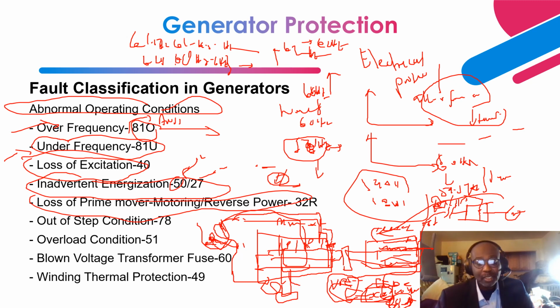So once the steam hits the cold water, basically it turns into a condensate. And there's a condensate pump motor that pumps the water. Then it goes through the feed water system and also the boiler feed pump. Then basically it goes back to the boiler. And the cycle is basically a closed loop. The cycle repeats itself, right? Okay.